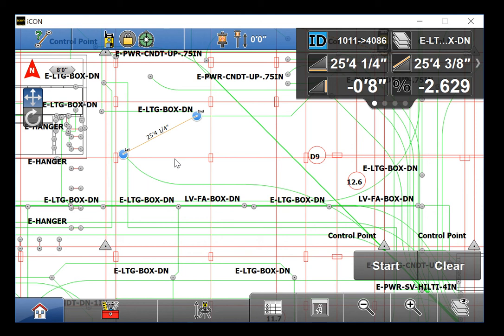The difference now is that if I select a third point, I will be provided the information radially, and it's always sequential from the last point I select to the point before it. Watch this example as I describe what's happening. By selecting these 3 points in a radial mode, I'm given the lengths of the 2 sides and the deflection angle turn between them.